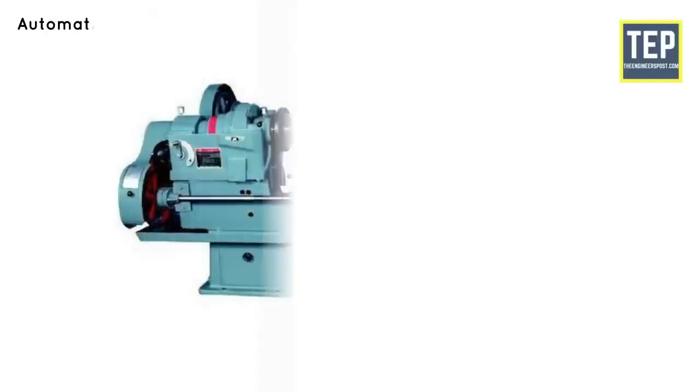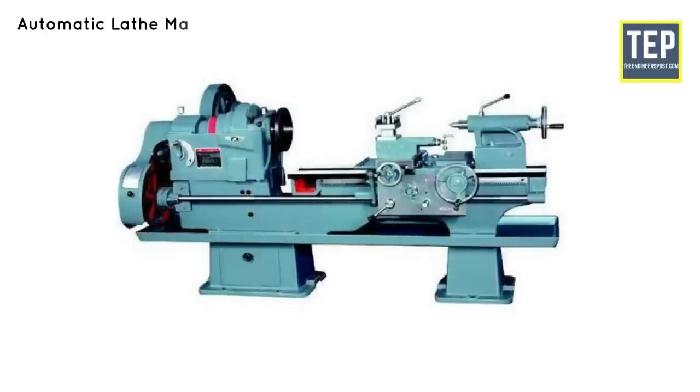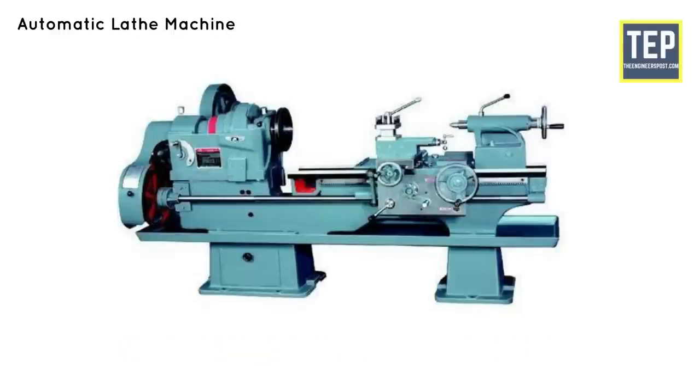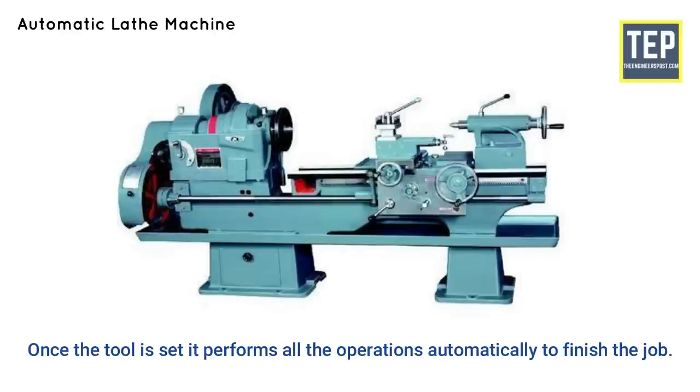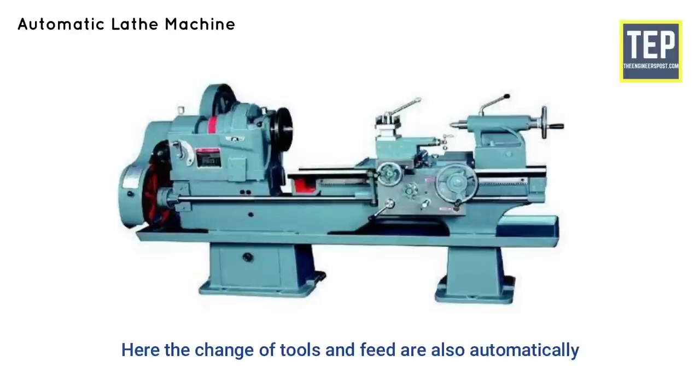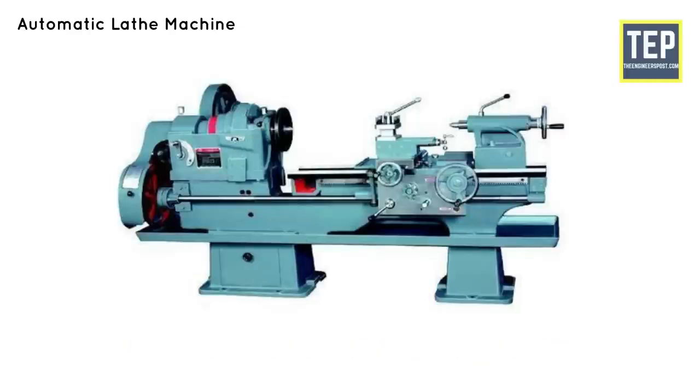Automatic lathe machine. In these types of lathe machines, all the work is done automatically. These are high-speed, heavy-duty production lathes. In automatic lathe machines, once the tool is set, it performs all the operations automatically to finish the job. Here the change of tools and feed are also automatic. A single operator can control 5 to 6 automatic lathe machines at a time.